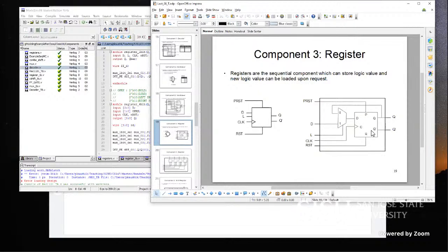At the end, it is a bunch of transistors operating underneath to make this functionality. You can imagine our 1-bit register has one multiplexer and one D flip-flop. Under the multiplexer, it has one decoder, a bunch of AND gates and OR gate.